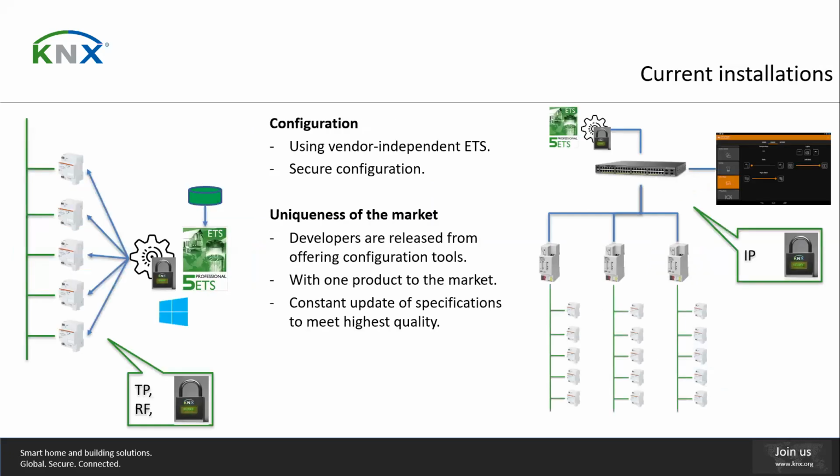Current installations. It is important to understand how KNX is installed, especially when you think of developing solutions for KNX technology. If we look at the left side, it's remarkable that KNX installations don't have a central controller. Each device has its own intelligence to be able to communicate with the other devices on the installation.